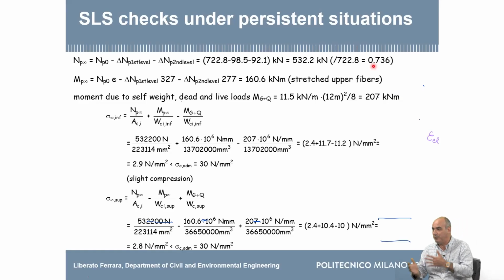one, 25, 27, 30%. More means that you are starting to go into some non-economical way of managing, because we are losing 30%. So if you lose more, it means that you must probably handle a better concrete, which shrinks less, which creeps less, or arrange your design in such a way that the creep losses are different.